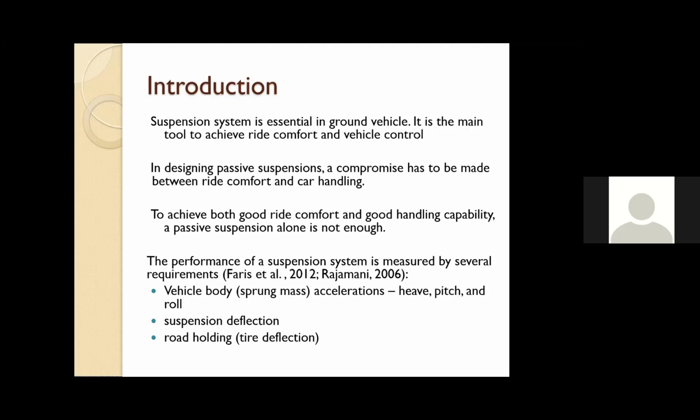And then from the suspension design point of view, we need to look into the suspension deflection, because the deflection is restricted by the space available in the car design. So we need to look into this as well. And finally, to have a good grip on the road, which will represent the car handling, we need to measure the tire deflection.